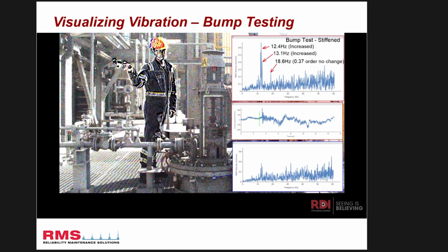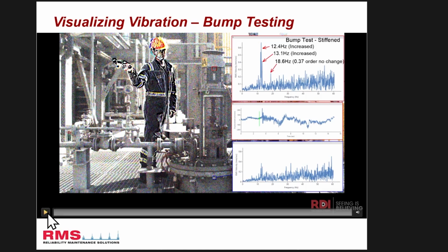In this situation, we've got a vertical motor and a pump. We can actually do it with a camera now, which is much better because it takes away the additional forces that you spoke about of the accelerometer changing the natural frequencies of a system. So I'll just play it, just show you what I mean by doing that.